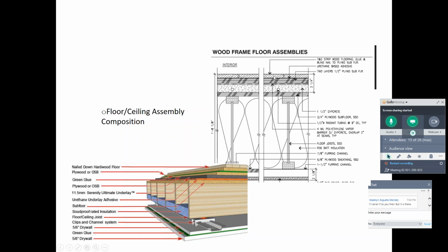Once we're more into our cross-hatching and we're using just line weights to delineate those things, it becomes a little bit visually confusing. Like we might memorize certain things, like most often, even though, let me look at my call out to see if it even shows it. Well, this curly pattern in the background is usually used for insulation. And then when we have our sideways dashing right here, that usually does signify to me a plywood subfloor, versus if I was going to have a gypsum or a concrete, which is going to be the dotted pattern.